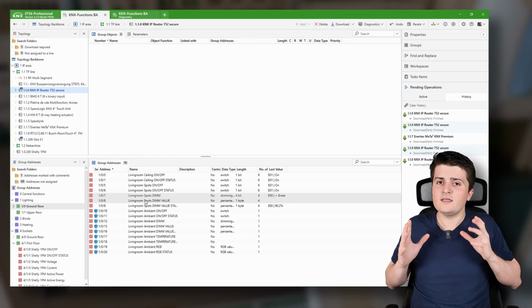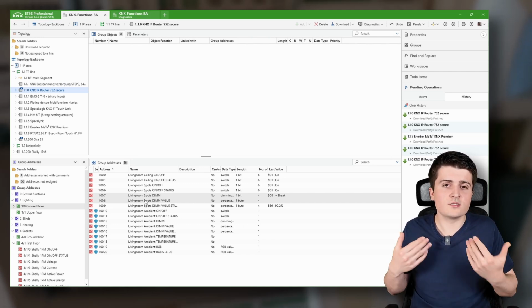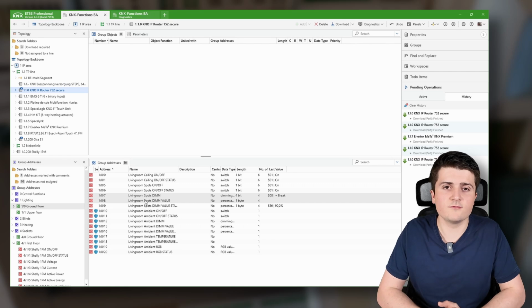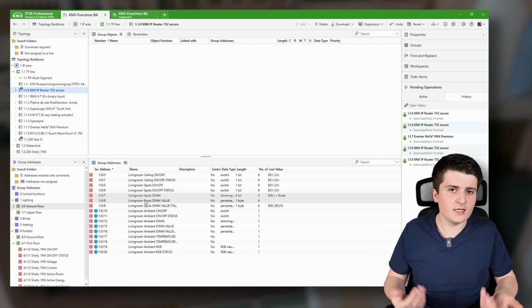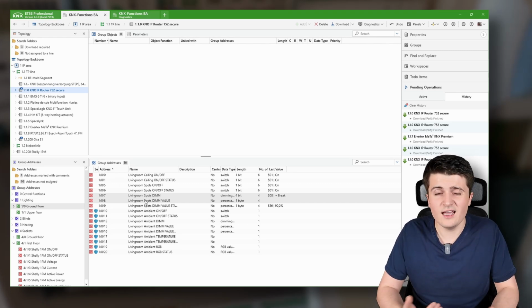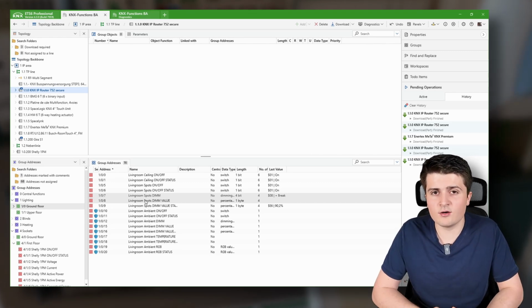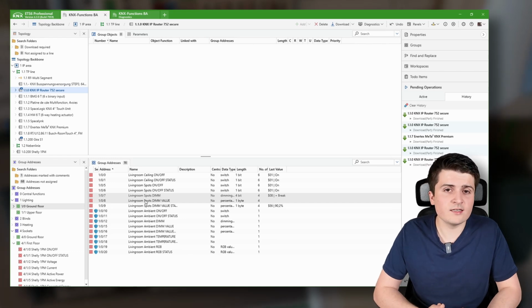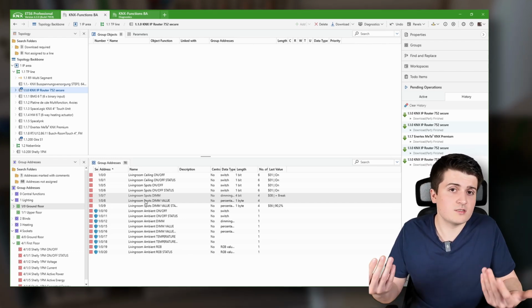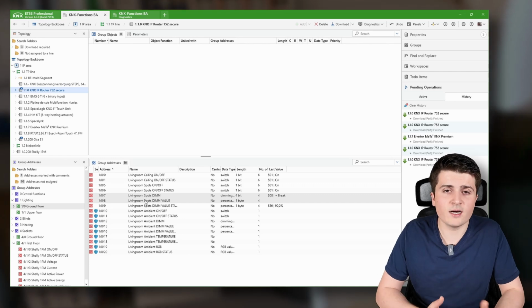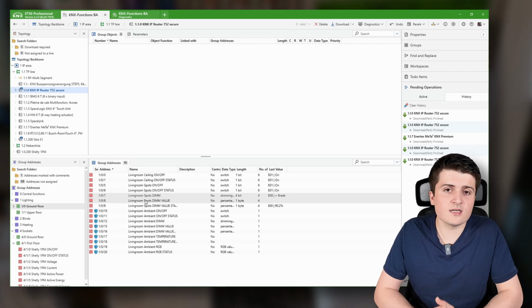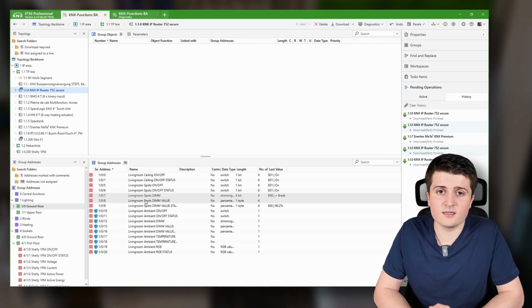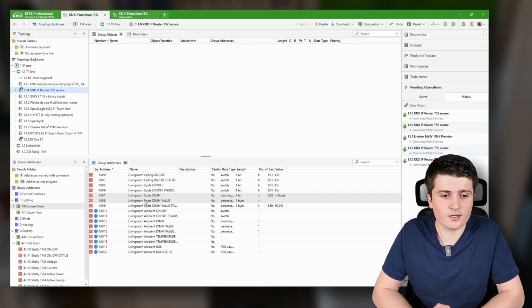I think it's a quite neat solution to simply quickly connect Shelly to your KNX devices, and that you don't need to have any, let's say MQTT to KNX conversion or something else. However, if I use KNX IP nowadays, I'll mostly use KNX IP secure to have it secured connection between my IP devices. But if I bring in my Shelly device, this IP connection, there I basically have to disable it. And so this is definitely something that you should bear in mind.